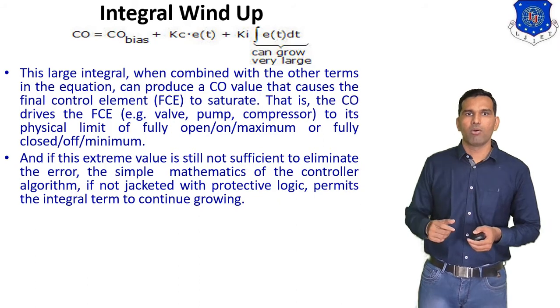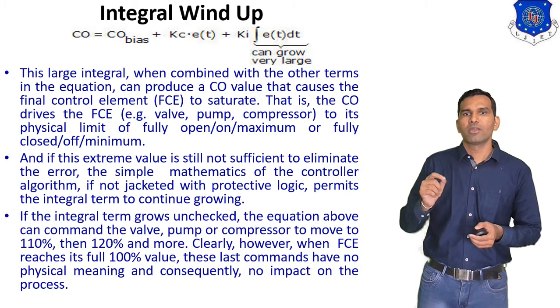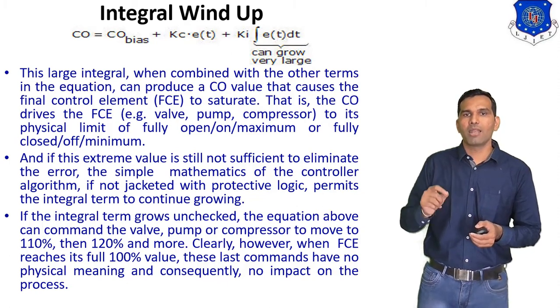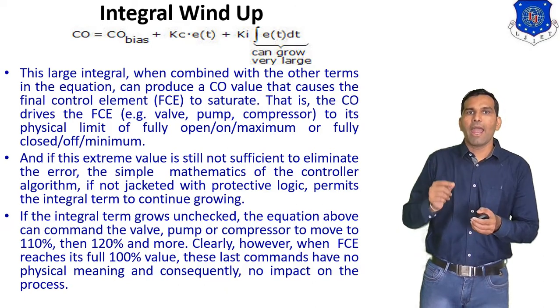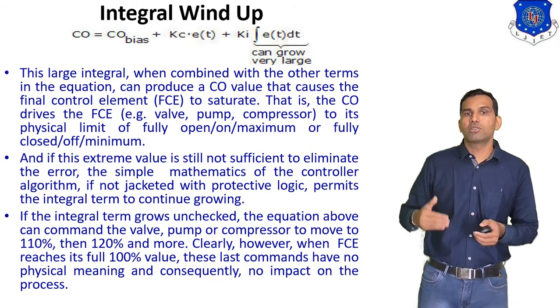Now we understand how. If the integral term grows unchecked, the equation above can command the valve, pump or compressor to move 110%, 120%, and so on.